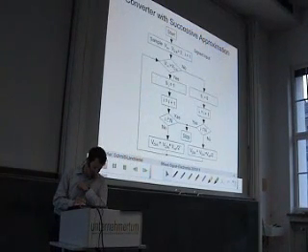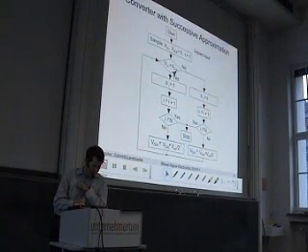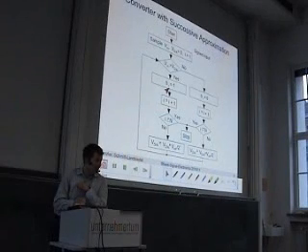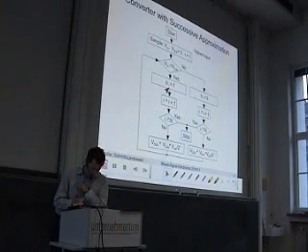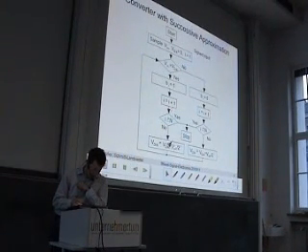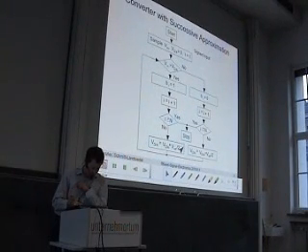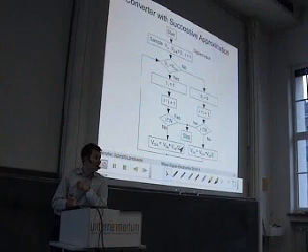So if the input signal is larger than the threshold, then we set the respective bit to 1. We increment the loop counter and we add a value here, which is Vref over 2 to the power of I, to this threshold signal.